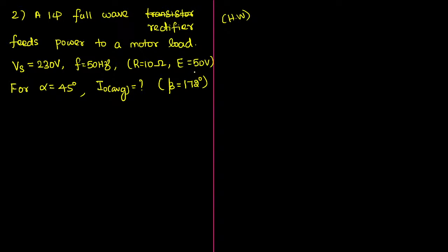Here they have tried to turn off this given circuit at 172 degree itself. They might use some external mechanism for this. It doesn't matter here and it is not at all required. But what is the actual meaning of extinction angle? Extinction angle means the conduction period of the diode is going to end.